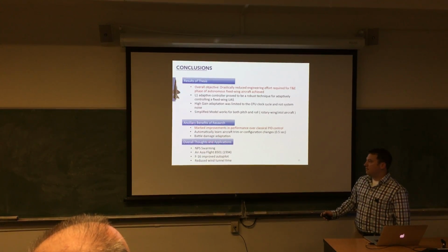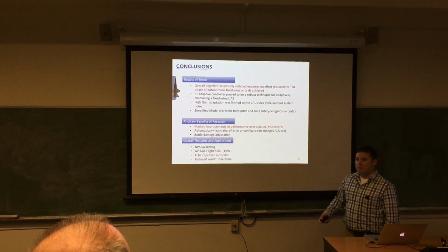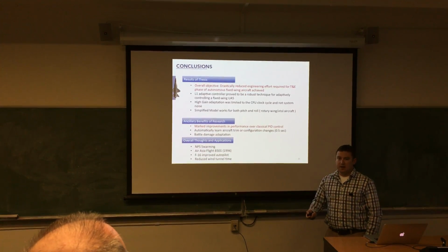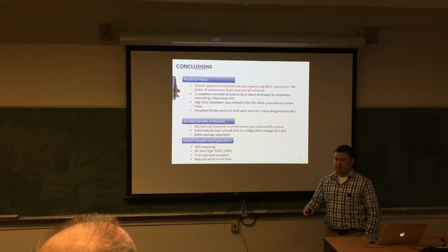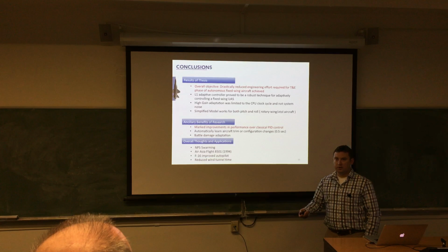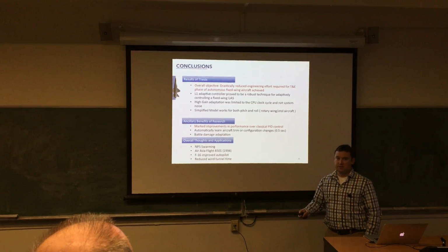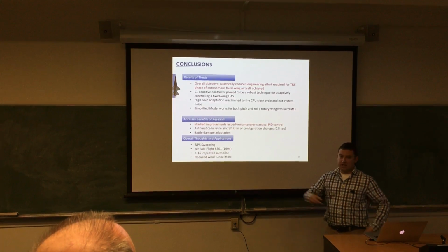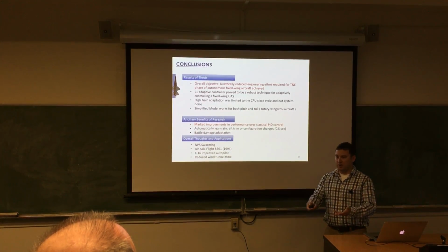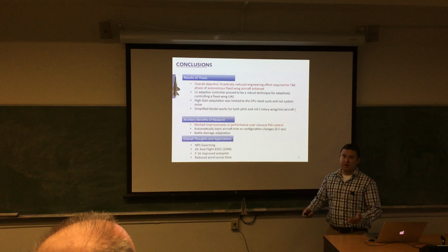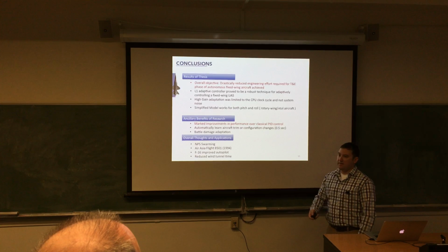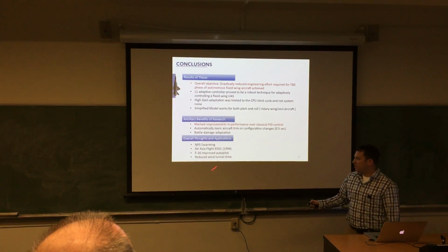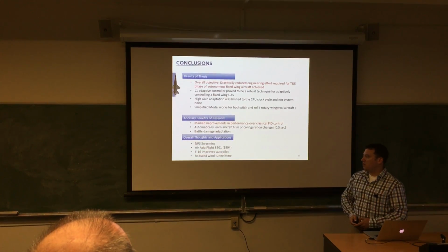So my overall thoughts and applications in the NPS swarming: you don't have to spend all that time painstakingly checking the center of gravity and all these things, because you don't care. The controller is going to learn the aircraft within less than half a second anyways. And it learns it on the fly all the time, in real time. So if anything changes, if you get hit by another aircraft, by say another swarm or something, it doesn't matter. It'll still fix it as long as it's within the control bandwidth and capability of the airframe in that damaged state.